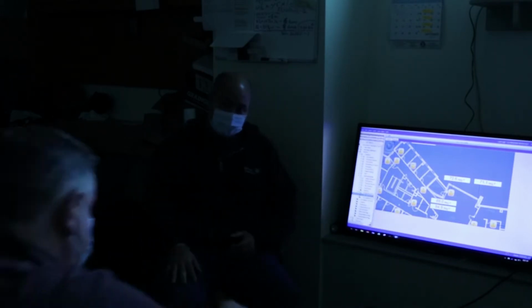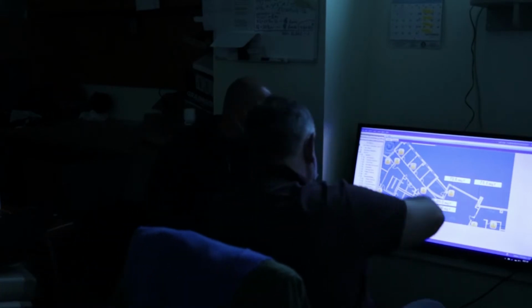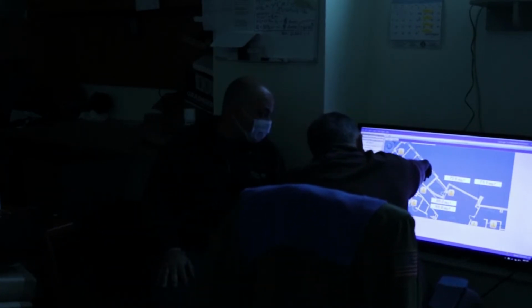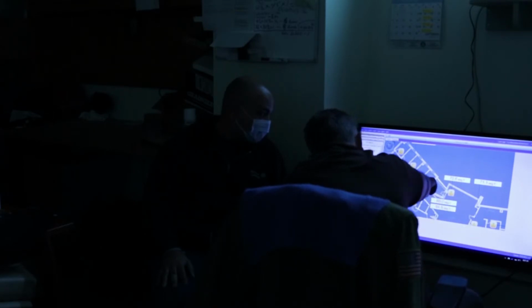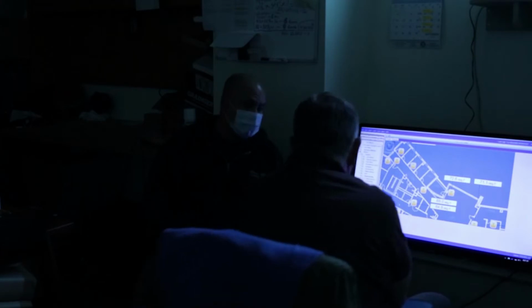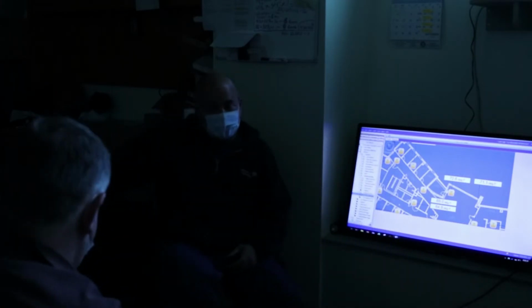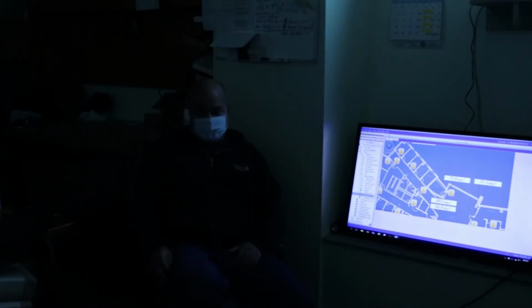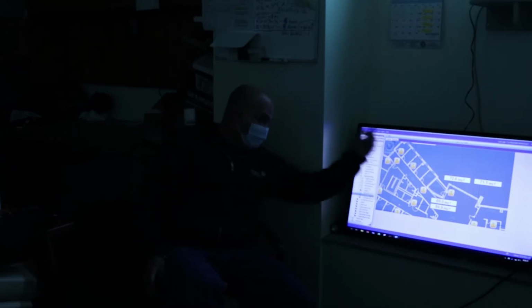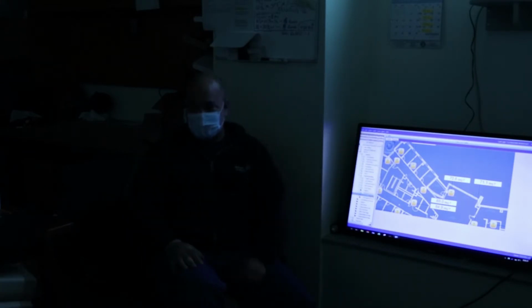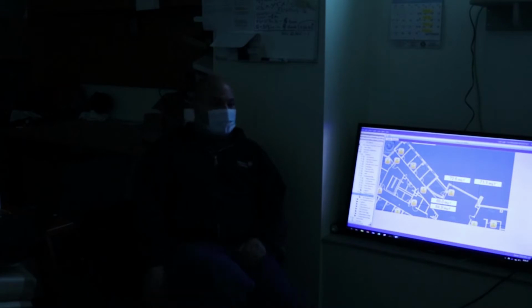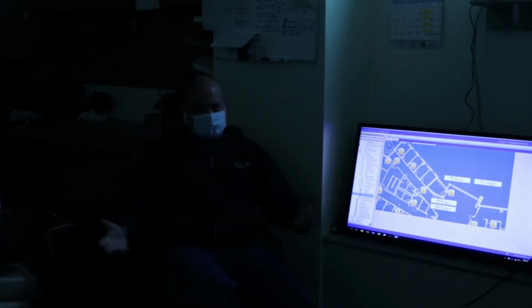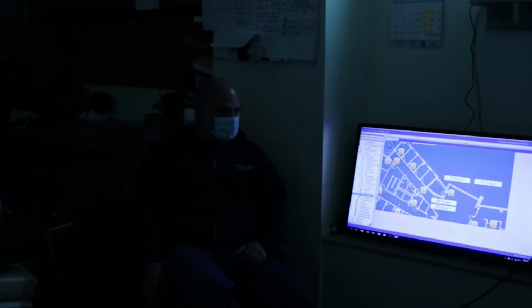Let's say a patient is satisfied in room 211 and the temperature is normal for him. Another one in 209, for example, says it's too hot for me. There's nothing that can be done. The only thing you can do is lower the temperature, and that'll bring the temperature down, but then the patient from 211 will start to complain. One thermostat controls three rooms.